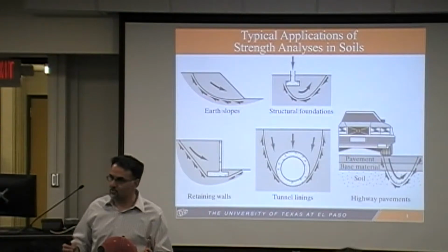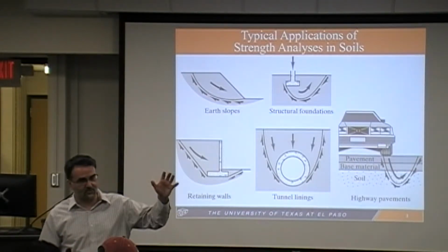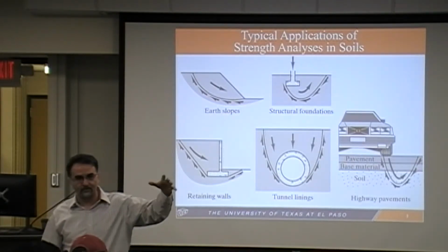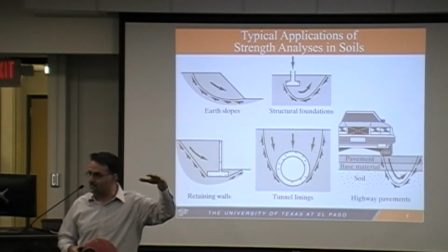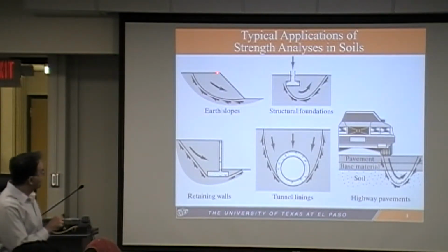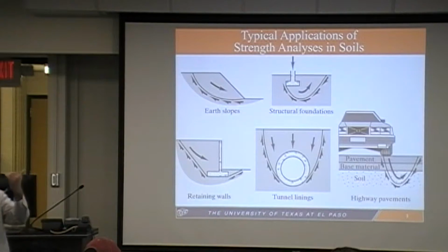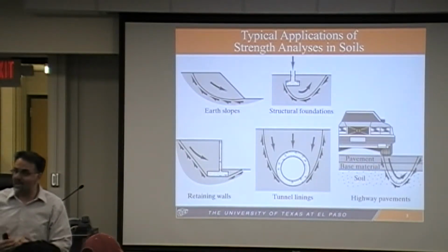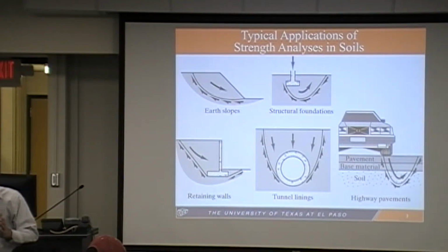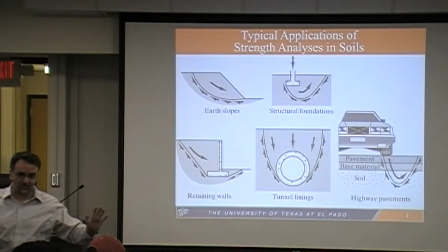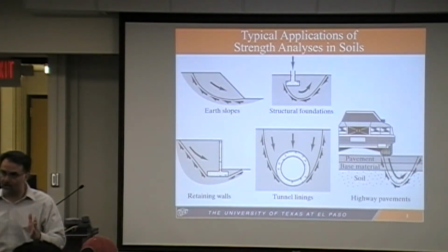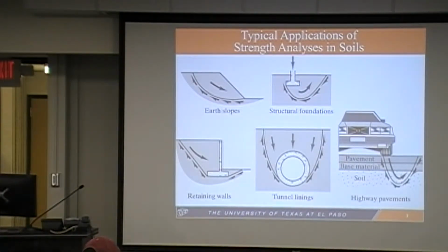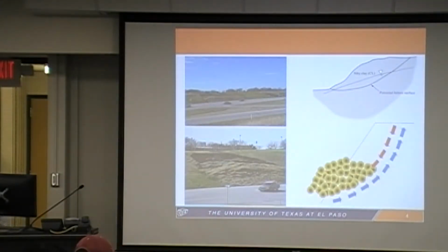Remember, in the previous lecture we talked about how it's not a good idea to have a concentration of mass at the top of the slope, such as having a pool at the top of the slope. Imagine if you have a pool right here that induces a lot of stresses, and that is in the rupture zone. You want to make sure that it is outside of that so it's not going to mobilize the soil along the way. So these were the general reasons for stability analysis.